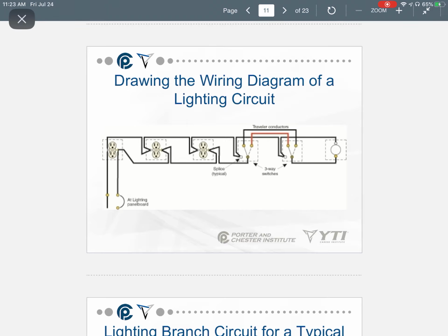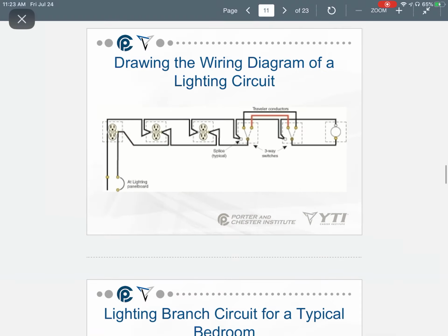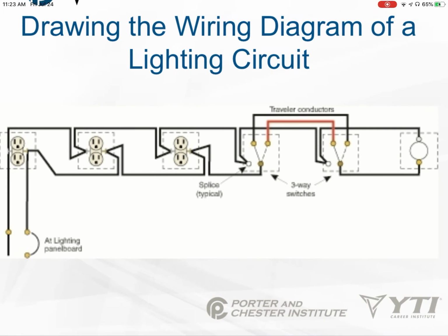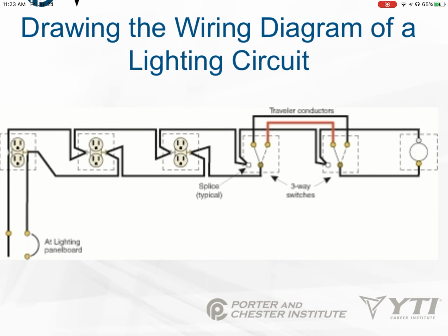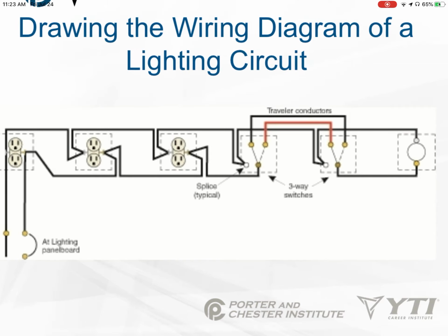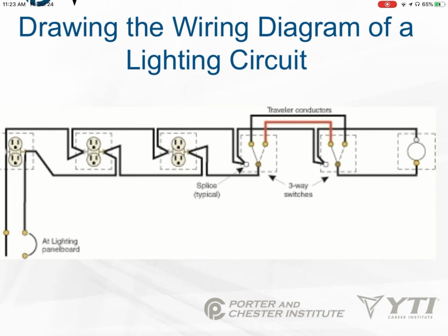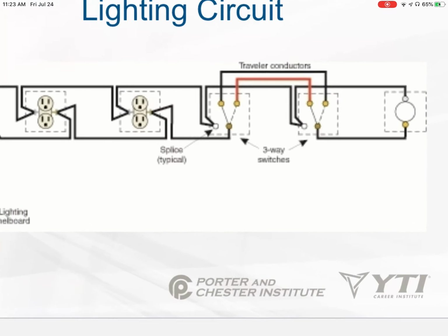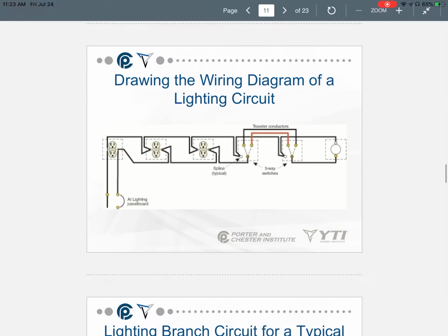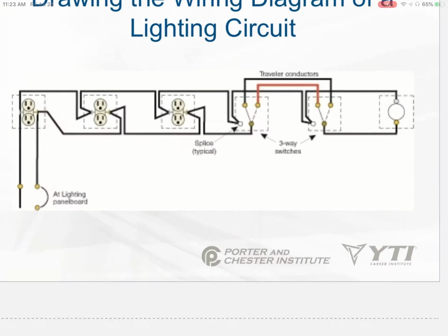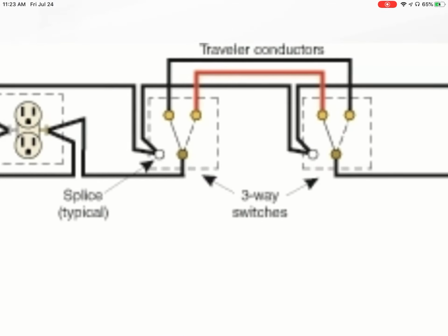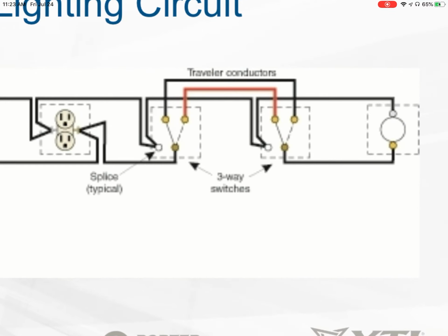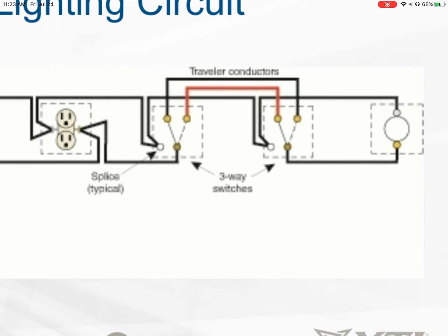And this is a line diagram, by the way, guys. And then we see from the breaker, we're hitting each device on the opposite side. Then we're going into a switch box. See that? We look here in the middle, right here. Stay zoomed there. So you see this? These little dashed lines indicate the boxes, the switch boxes.